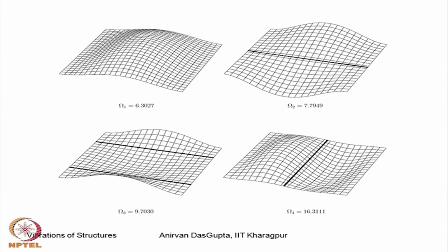In this figure I have plotted the first 4 modes of the plate. You can see these edges are the clamped edges. So, the straight edges are actually the clamped edges. You can see the displacement, and of course, the displacement and slope will be 0 because the geometric boundary conditions have been satisfied. Now, here this is a stiffened edge.